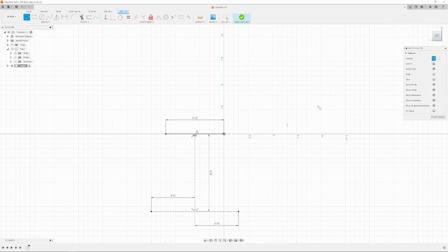And then now all my lines can be solid again. So I'm going to deselect construction. And you're looking for a funky shaped leg now. So we're going to start from the end point and go down 2 inches from each of these lines. We're going to do that because of the shape of the leg.